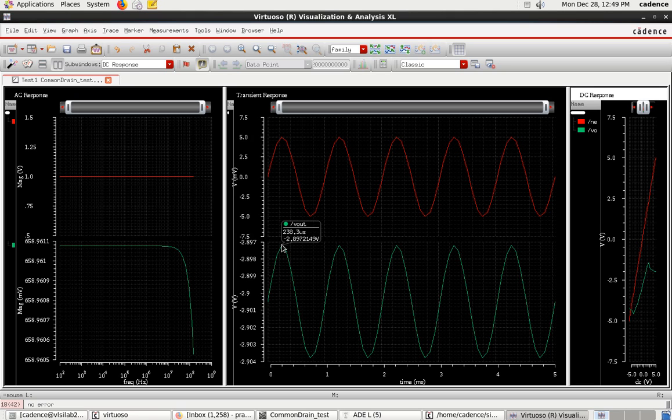That means with the consideration of parasitic effect, around 1 millivolt has been lost, right? So that is the difference between pre-layout and post-layout simulation. That means in the schematic you were expecting 7 millivolts of peak-to-peak voltage at the output, but here you are getting 6 millivolts. That means there is a slight difference in the gain, around 0.6, with consideration of parasitic effect. So you have to compare pre-layout as well as post-layout simulations, right?